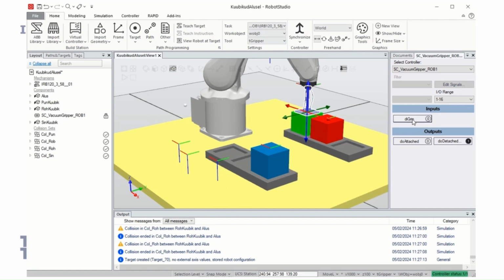I do recommend to switch off the gripper once you have taught all the positions. Then, on the other part, be careful with this move function or rotation function, because it can not only move the robot tool itself, but it can change the location of the components. So if you don't need to use it anymore, then deactivate it.